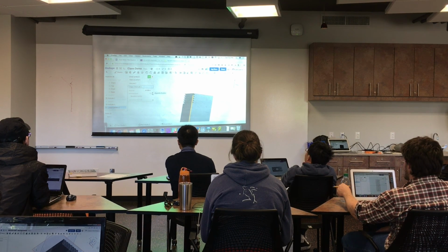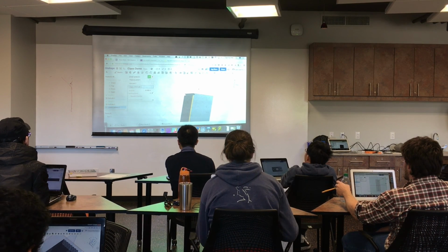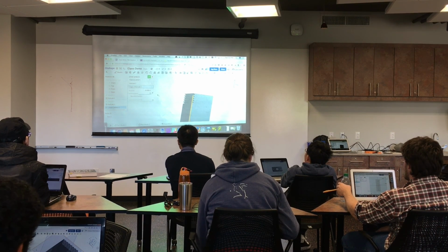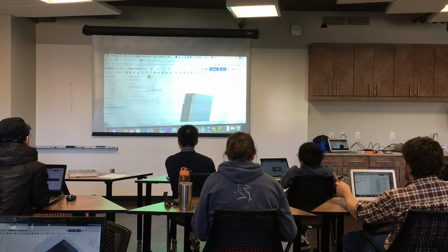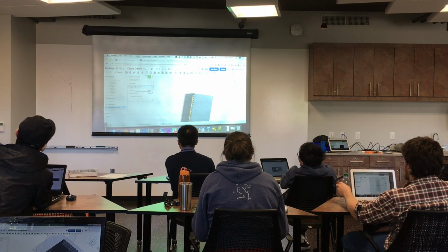There we go. If we flip the direction, now we have 5 of them. It was trying to put them off this end. Now we're going to say we want 150. It's going to think for a second. We're going to have 150 teeth.